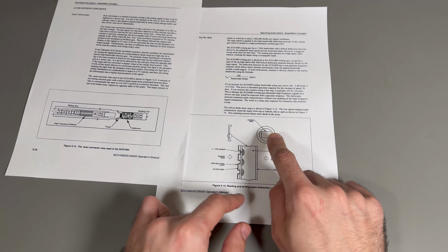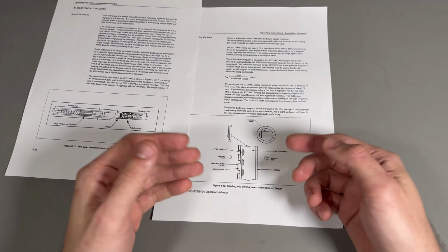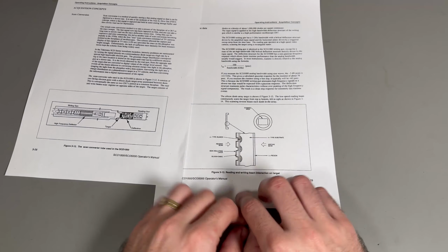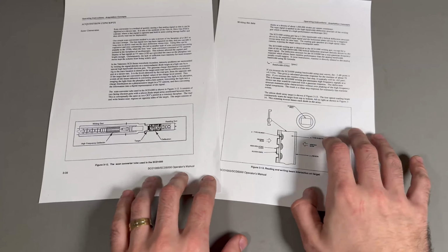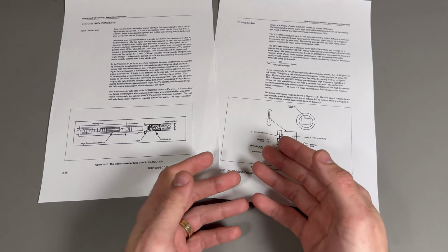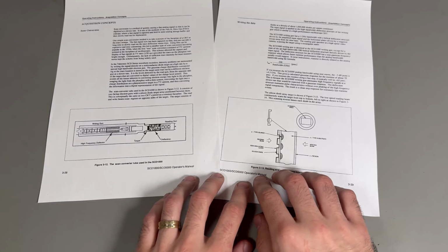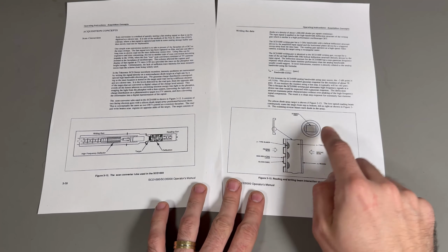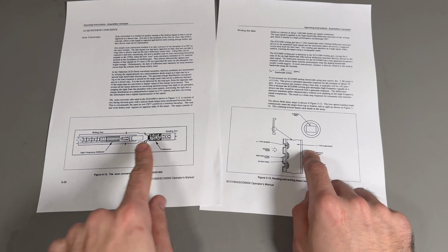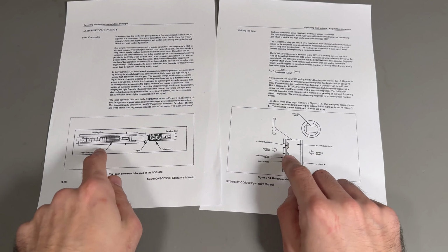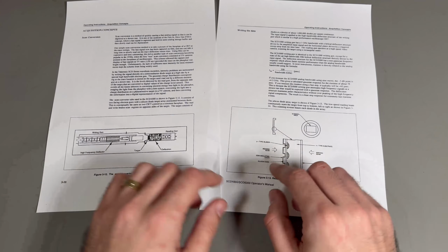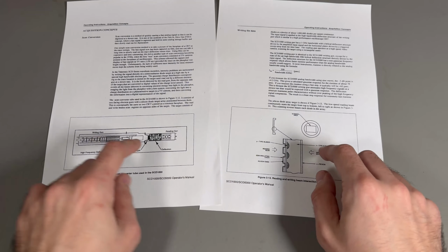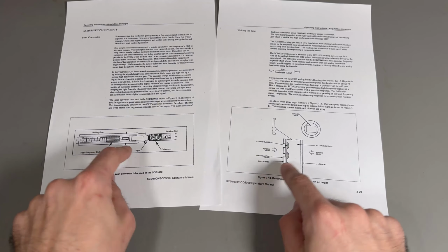Now, the beam current is gonna be higher or lower depending on whether the target has been illuminated in that area or not. So this is a way of acquiring very fast signals with not very fast hardware, because the scan of this takes quite a lot of time. The write bit is very, very fast, as is the whole purpose of the device, but you read it off slowly. So this is fast in, slow out.